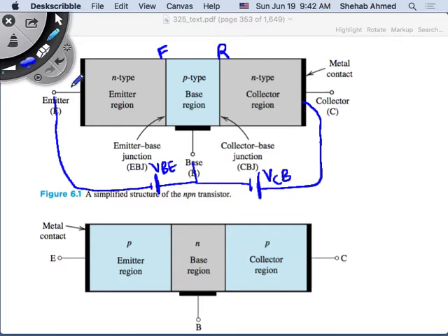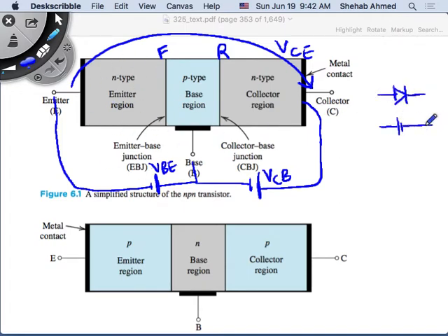Now the voltage between the other two terminals is called VCE, right? When this is forward biased, as with any diode, I have a model that tells me there is a voltage opposing the current flow equal to VF. In a typical silicon diode, with similar-sized PN regions, this VF is about 0.7 volts. So this will have a forward voltage of 0.7 volts across it.